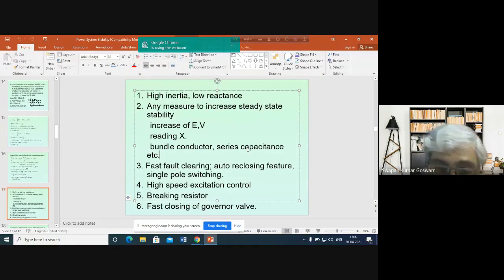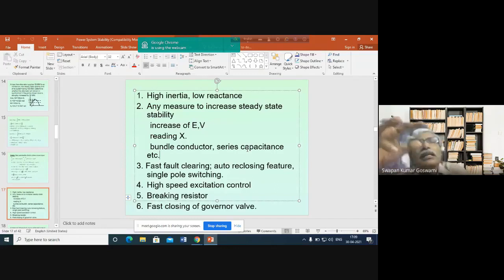If series resonance occurs at those subharmonic frequencies, some very small current that would otherwise flow through the system will actually increase, because resonance is occurring.